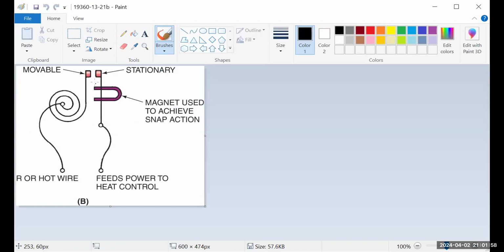And then when you heat up that bimetal, it's going to warp one way or another. They can mount a mercury bulb on the top. So when the bimetal tilts one way, it calls for cooling. When the bimetal tilts the other way, it's going to call for heating. So that bimetal is used a lot to sense room temperature and also temperature of components too.